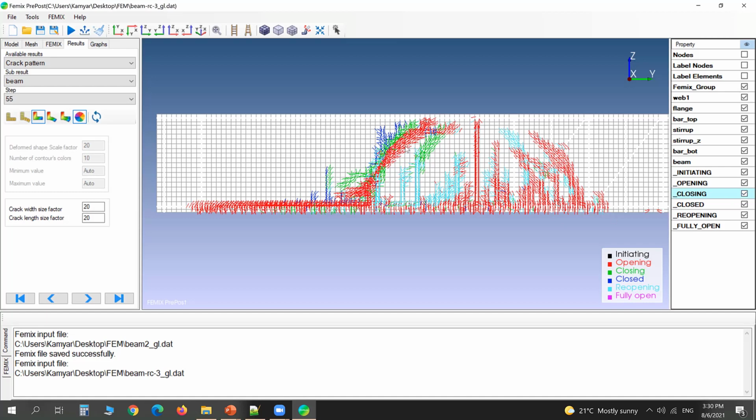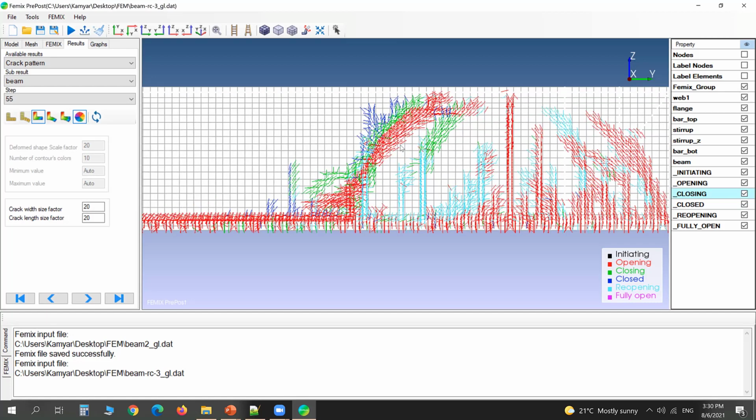The crack is opening, and since this zone is opening, the stress is decreasing because it's a softening. And in surrounding zone, we have an unloading stress state, and this is the green crack. So the cracks start closing. So this is quite nice, and this is what happened in reality. Okay, thank you. Exactly. Okay, and we have different outputs such as stress, strain, and then we can go to the graph.